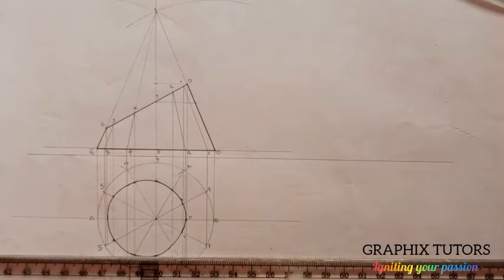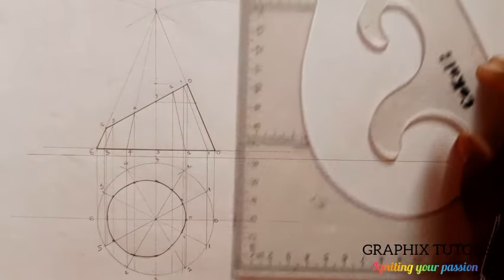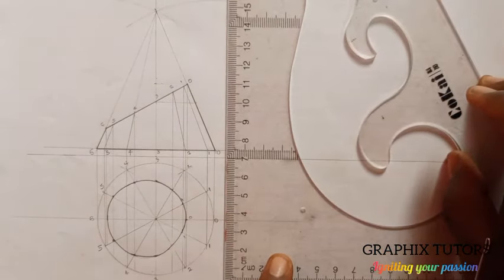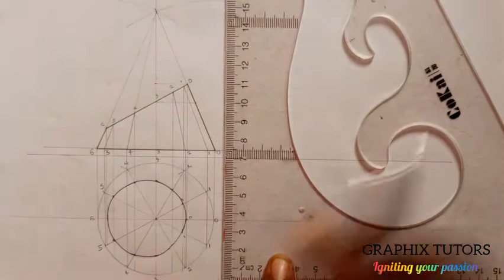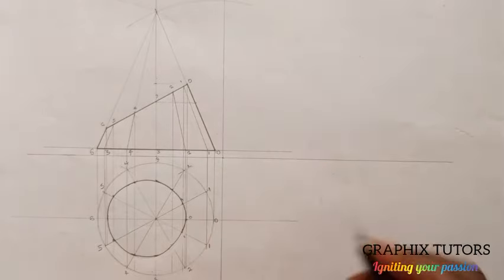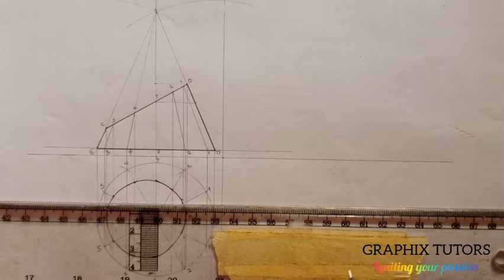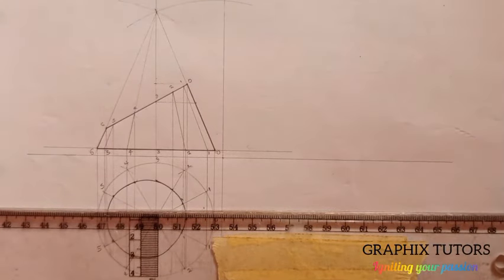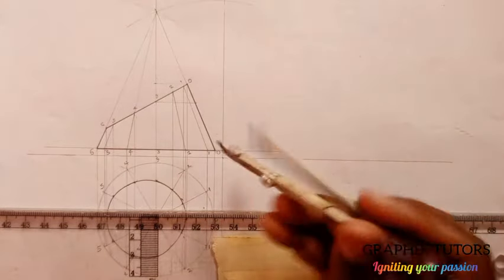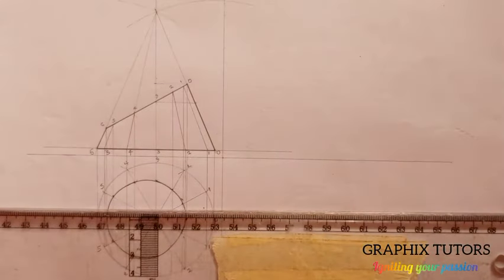Then I'm going to draw another vertical line, as if I want to do orthographic projection. Another vertical line here. So let's draw that at any radius of your choice. Right? Now they are meeting at this point here. Now, what I will do is take this same measurement here, the measurement I used to get this point. Or better still, I will just draw my 45 degree at that point.